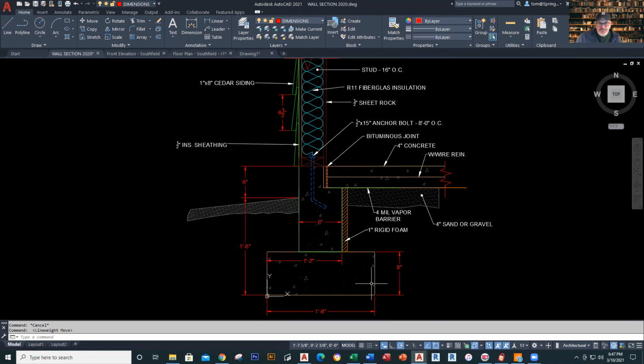Okay, now that we have this, the next thing I have to do is begin to orient this wall line right here. So that wall line comes out here. The wall is 8 inches thick and it comes off the front. The back end of it is 1'2". So it comes 1'2" off of here, and then it's going to go up a distance right here. Now I don't have this distance right here, so that one I'm just going to go ahead and start. This one over here, I know this goes from 1'6" up to this right here, and then the bottom here is 6. So the total distance here is 1'6" plus 6, which is 2 feet. So it goes up 2 feet.